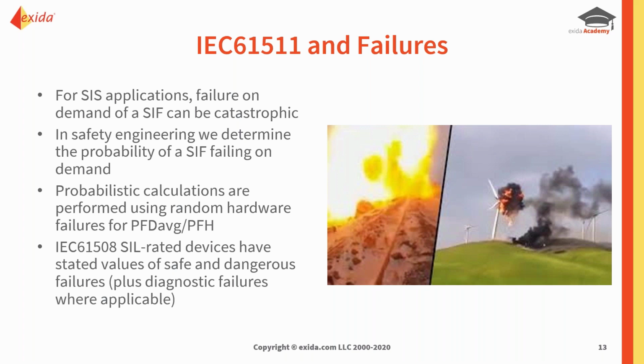Now, we know that in a SIS application, we expect the SIS to be able to respond to a demand. And the thing about safety instrumented systems and safety instrumented functions in the process industry, the majority of the time, we are looking at low demand applications for the SIFs, which means that they're going to be sitting there static, not doing anything for very long periods of time until a demand occurs.